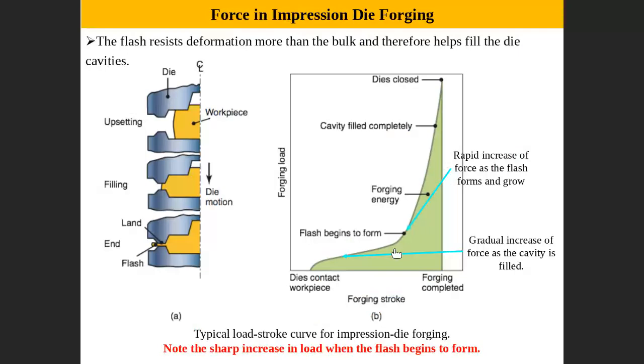And you can see upsetting starts here. Can you see that? This is the half cross section. Upsetting starts here, more upsetting. Flash has started, as you can see, and as you apply more, the flash is getting bigger and the material becomes very difficult to flow. This one applies back pressure to increase.